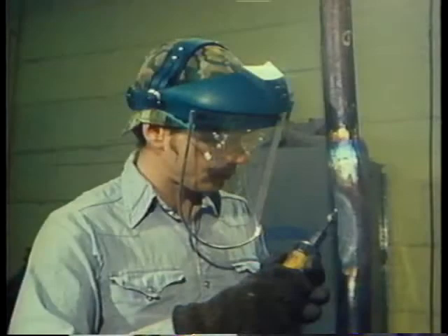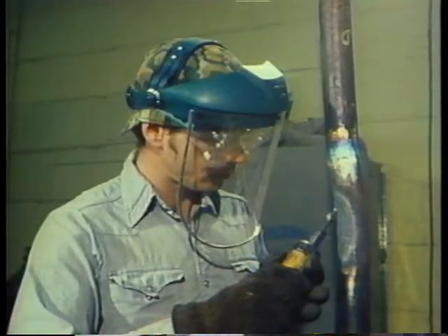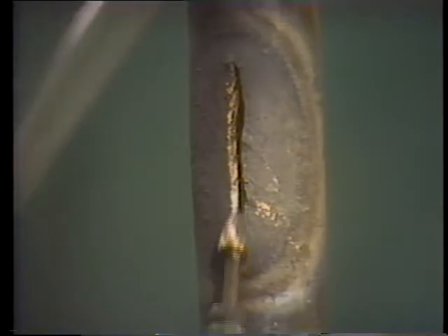Whenever you're near a grinding operation, wear face protection. Ear protection may also be required. The full length of the opening should be ground, paying particular attention to the ends. The tapered ends should be ground so that they are rounded. This is important because the tube can rupture in the exact same place unless the ends are completely ground.